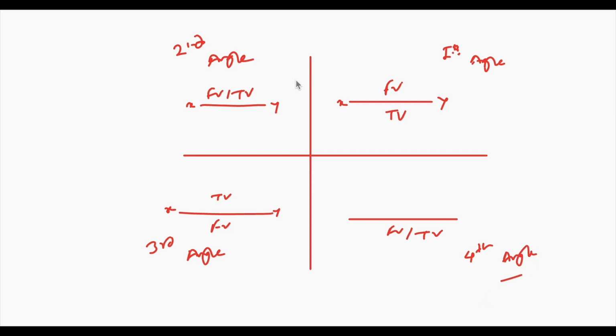So as there is overlapping of views in case of second angle projection method above the XY line, and in fourth angle projection method overlapping below the XY line, the second angle and fourth angle projection methods are not used. The remaining two methods, the first angle and third angle projection methods, are extensively used to draw various views of the object, and specifically in the Indian continent we use the first angle projection method, and some European countries refer to the third angle projection method.